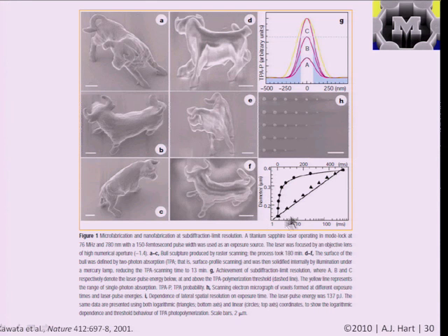And if you were to look at this paper, you'd also see that they did some studies, for example, for how much exposure time they needed to make certain features, like these circular dots like so, and they also explored the smallest features that they could make by this technique. And one of the underlying principles is that within the focal spot of the laser, there's a thresholding effect that occurs, that when you get two photons to hit a certain point, there's a very sharp transition between the area where you get this exposure and where you don't get any exposure, and this is significantly smaller than the wavelength of the light. So it can beat it by a factor of a few, in addition to being able to be restricted to the focal volume of the laser. And here's another example of structures that were made by this technique.